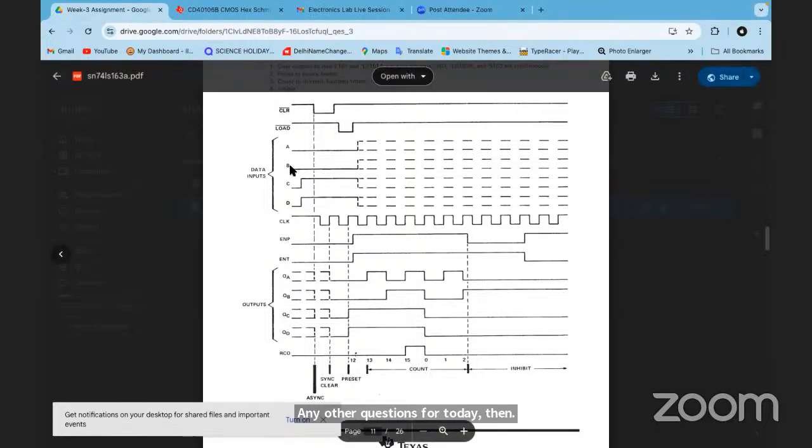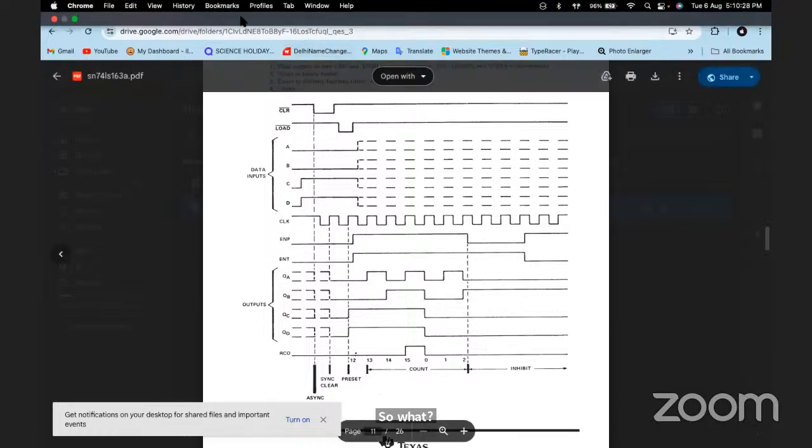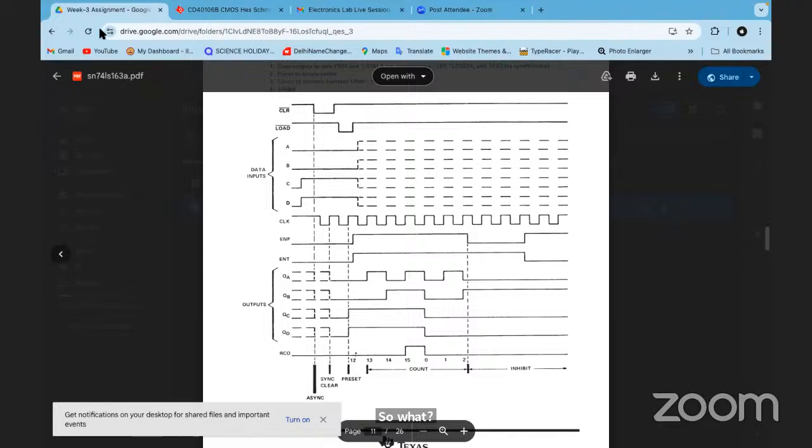Sir, Namaya is not in the meeting, I think, but he has done it with the 555 timer. Yes. So like I said, this experiment is very simple. The idea is to see that voltage is not sufficient. There can be other issues also, which could be current, or like that gentleman said, it could be something else which we need to look at. Just because you get a voltage that looks okay, it doesn't mean everything is okay. That's your main learning from this experiment.